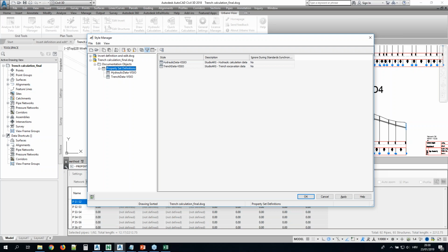So it goes to IFC, for example, and you can use it to add to labels. So it's flexible, and you can write your own data in it, and so on. So it's very nice, but unfortunately the use in Civil 3D is a little bit restricted, and there is so much more that you can do with property set data.